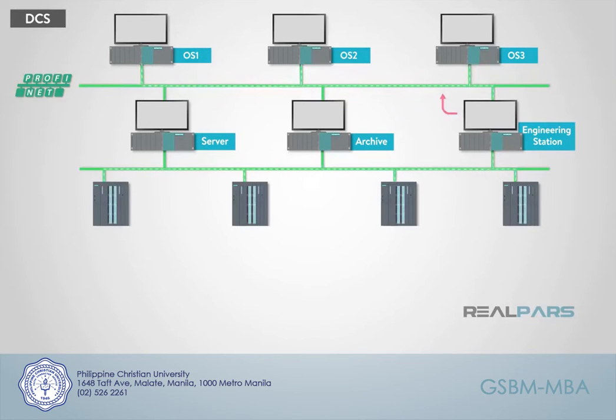This is the station that is used to download the projects to the processors and the graphical displays. At the next level, you have the master controllers that supervise the individual processors as well as I/O modules. These controllers are also responsible for providing the data to the servers, which in turn supply the data for the graphical interface. Industrial Ethernet is typically used for communication with the previous level. Fiber optic may be used here when Ethernet cabling runs would be too long.